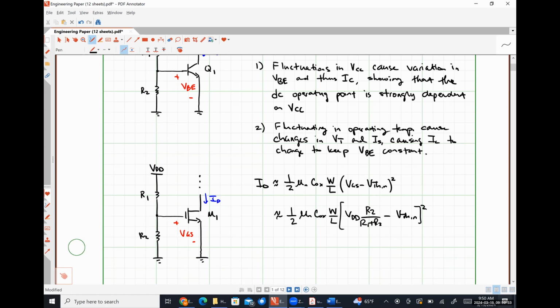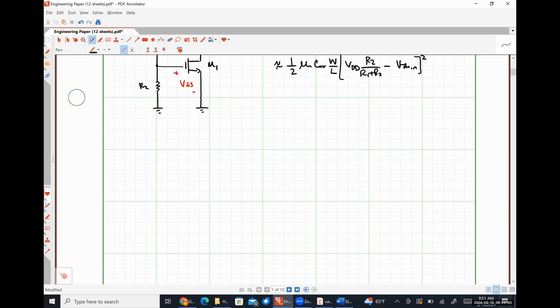So in order to mitigate that, people much smarter than me have come up with different schemes that are based on effectively temperature invariant quantities, okay? So in order to generate supply and temperature independent voltages and currents for high performance microelectronics, people have devised circuits like the one that I'm about to draw. And by the way, this is a simple one and it's still real gross, which is called a band gap reference circuit.